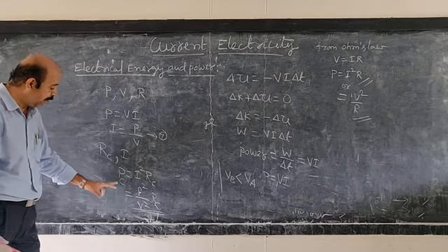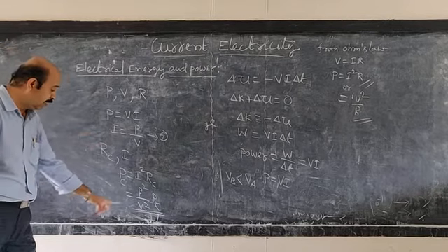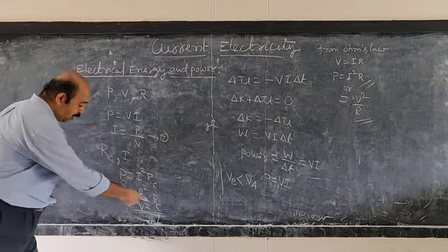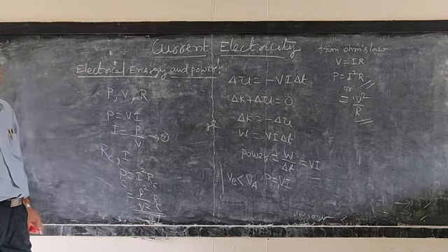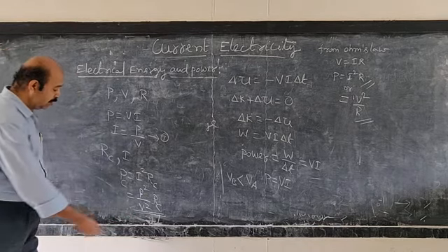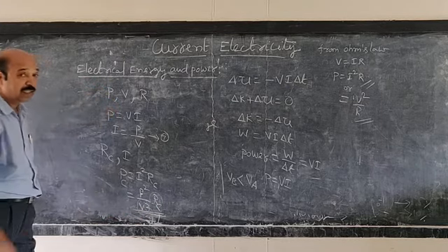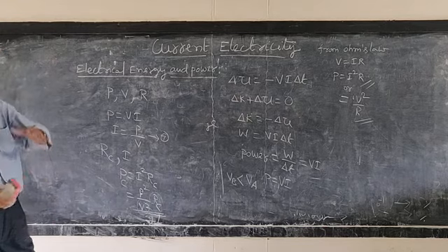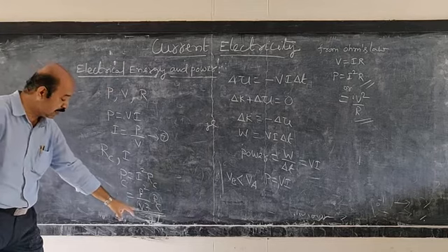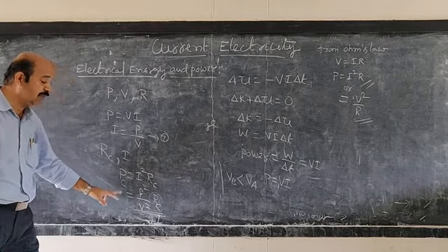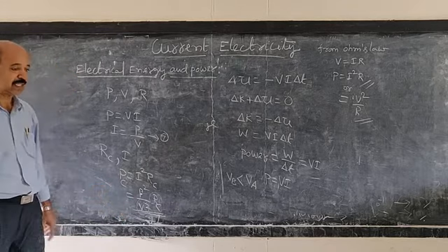The power loss or the power wasted in the transmission cables is proportional to the cable resistance and inversely proportional to the square of the voltage. This term is more important because it has a square. Therefore, if you transmit the power at high voltage, since it is in the denominator, the power loss PC will be lesser. So as you increase V, PC decreases.